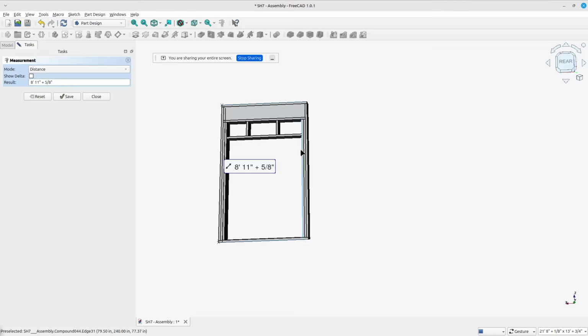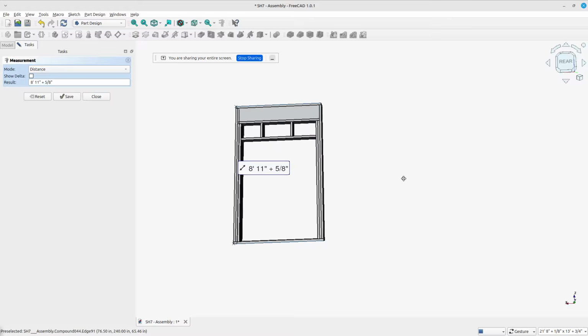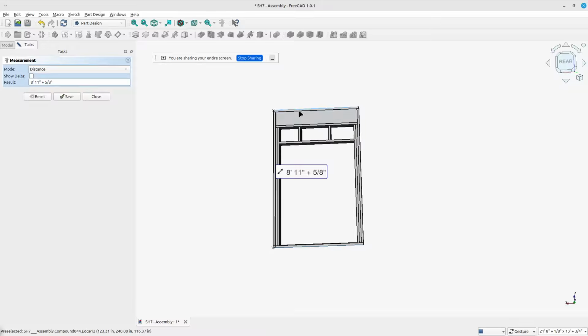Yeah, and we can do the technical drawings as well, so we can do various ways to do this. When you're viewing it within CAD, you can get those kinds of measurements. But the point is to play with FreeCAD and make sure you can replicate steps exactly like what I'm doing here. If you want to get a distance, mode distance, reset between, you can select two parallel locations. That's quite useful. That can cover a lot.